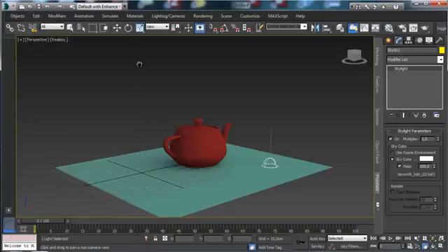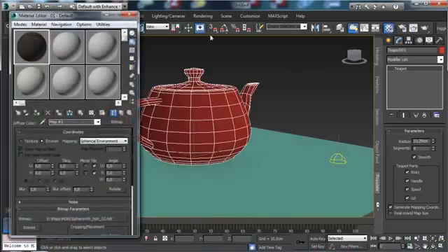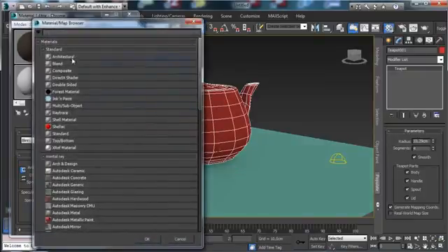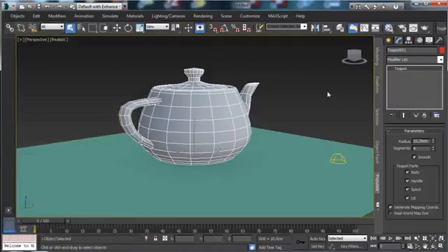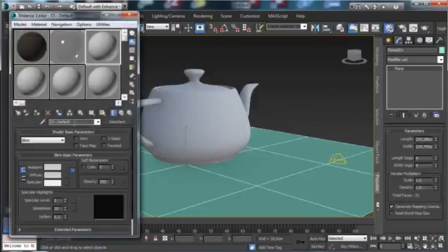And first of all, a really interesting thing is that we are using the HDR map to simulate the illumination also inside the viewport. So this one is the right illumination coming from this point of view there, and that's really interesting. Let's give, for example, to this one a chrome material, and let's do it using an Arch & Design. We use the basic template using the chrome, and we can assign it. Okay, so that's our sphere.